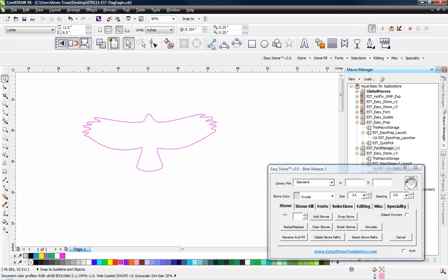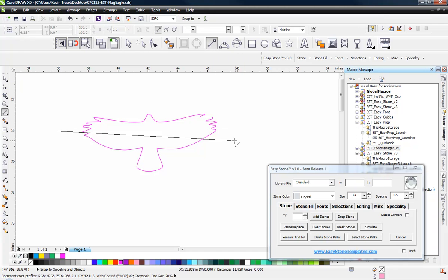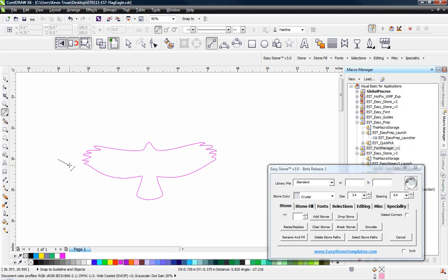The next thing that we're going to do is we're just going to come in here and draw the 2-point line tool. I'm going to try and use as much of CorelDRAW as I can, and the reason I'm going to try and do that is so that you have a good understanding of CorelDRAW. The better understanding you have of CorelDRAW, the better designer you're going to be as it comes to designing anything, really. So we grabbed our 2-point line tool, we picked a point, we're clicking and dragging with our mouse. If we hold the Shift key down, it'll constrain that horizontal line, vertical line, or certain degrees.